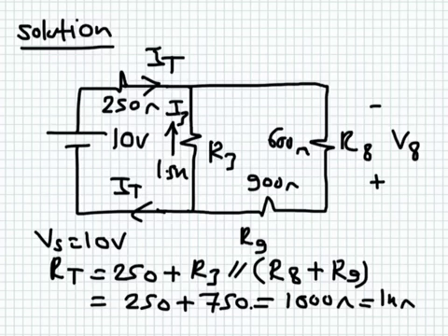So now when you draw the circuit, the circuit looks way nicer. I combined 120 and 130 ohm to just 250 ohm, and this is right because they are in series. The same current is flowing here, the same current flowing here. So the battery supplies a current of I total, and this current will split into R3 and then into this branch. So this branch here and this branch here are in parallel.